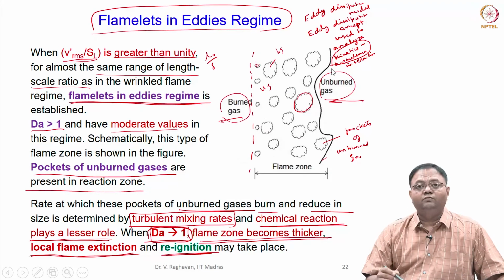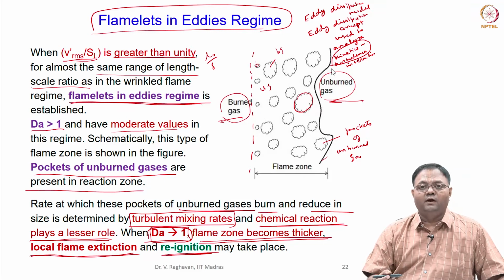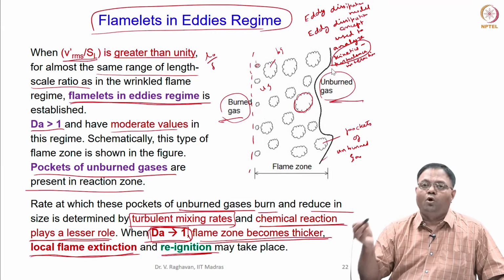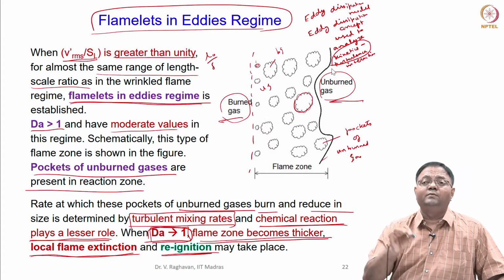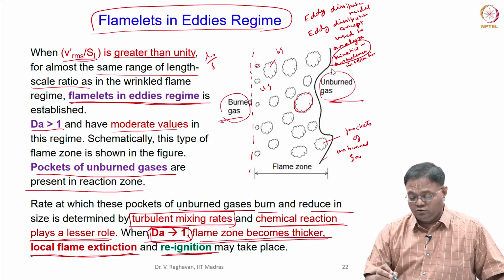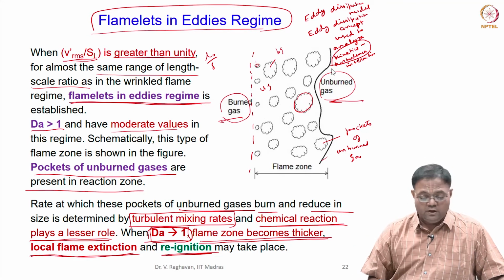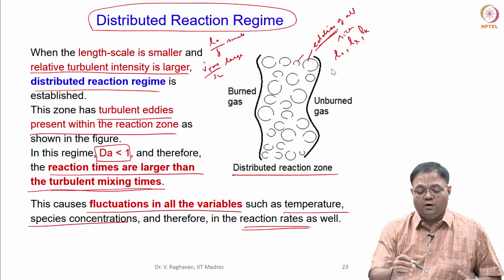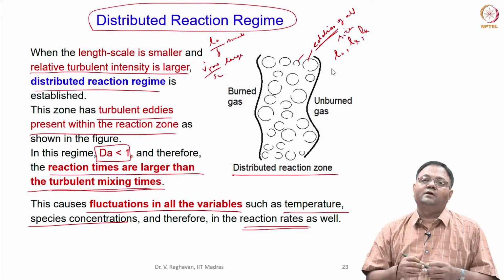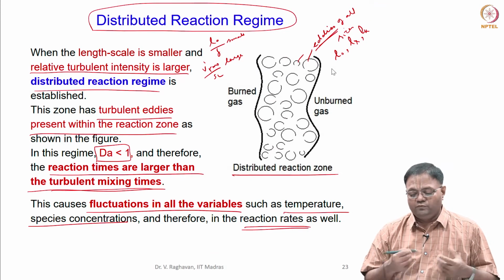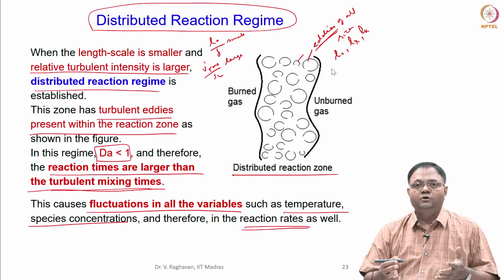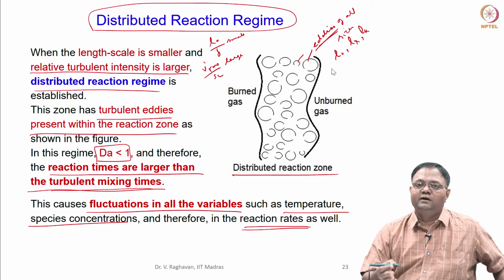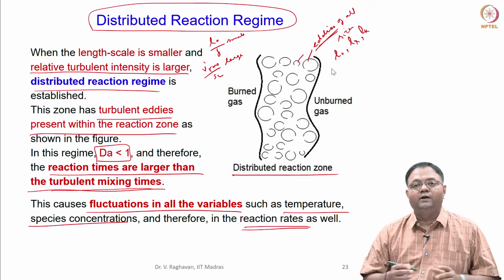In the second case, we have to use chemical kinetics. However, we also have to take care of the interaction between the turbulence and the chemistry. Third will be the zone where the chemical kinetics can be discarded, and only a model like the eddy dissipation model can be used to predict it.